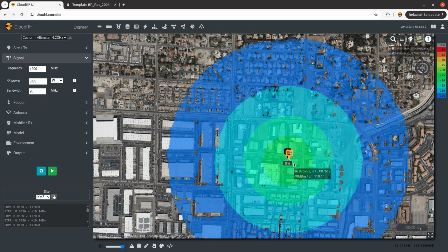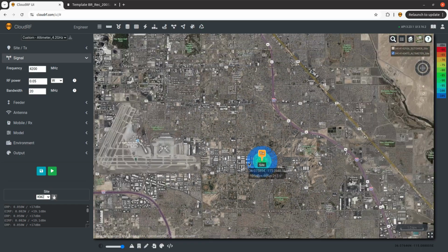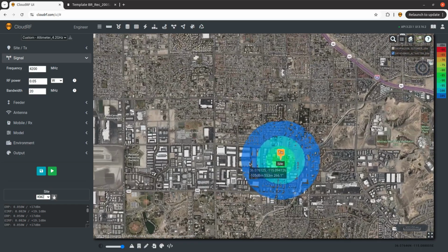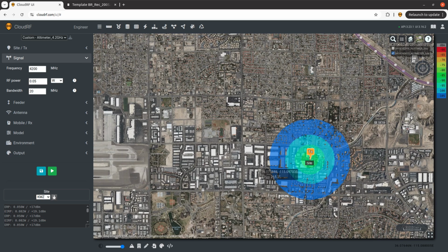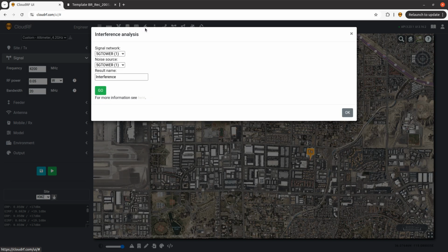So this is 100 meters altitude looking straight down, and this is used by the computer to gauge the height in zero visibility. So you hear people talk about a CAT III ILS approach. That's zero visibility under computer control. So it's very important the computer is measuring the ground accurately. So what we're going to do is model that cell versus a radar altimeter, and it's on the flight path. Not a great place to put a cell.